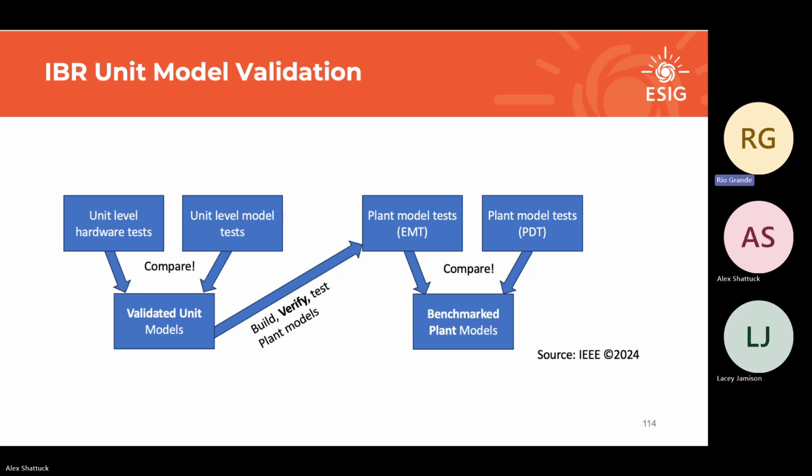So when it says validated unit models, it could be the inverter, or it will be the inverter, it will be the plant controller. If you want to go crazy, it could be the SVCs or other switching controls, but those are usually smaller OEMs who don't always do this huge type testing. So you might have troubles getting that type of data from them. So what you're building, yes.